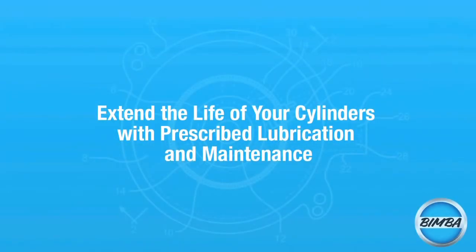Extend the life of your cylinders with prescribed lubrication and maintenance. Recently, cylinders permanently lubricated from the factory have become much more popular, lessening the importance of maintaining proper lubrication levels through the cylinder's life. However, for cylinders that require lubrication, one of the keys to maximizing the life of pneumatic cylinders is maintaining the proper lubrication levels. Cylinders that are not sufficiently lubricated can overheat, causing damage to components and degradation of seals.